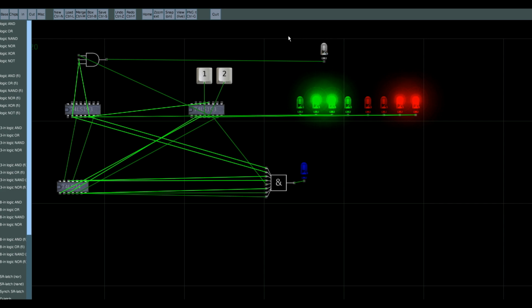What I've also done is taken all 8 bits and I've passed them to another chip, which is the 7400 series 04. It says Hex Inverter. What it actually does is it takes each input and it will NOT it.